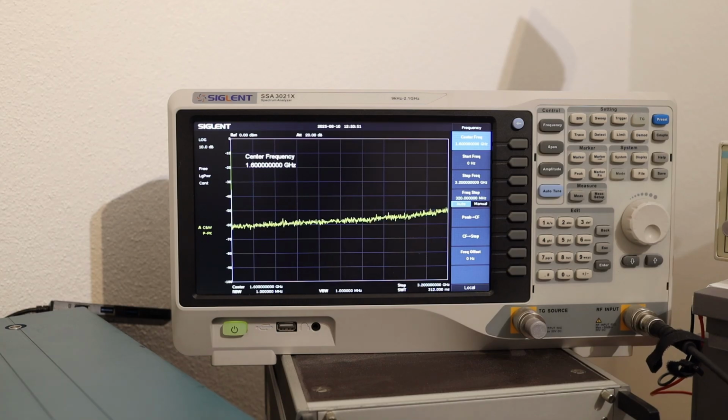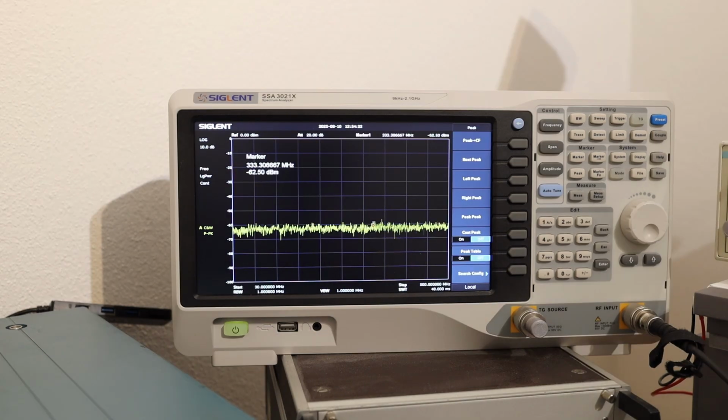Now we'll operate it from the computer. So we have limited the span from 30 MHz to 500 MHz. So let's output a 50 MHz signal. We'll write, maybe we'll select auto write. Let's turn on the output. You see that at 50 MHz I got -1 dBm of signal available. Primary output is at 50 MHz.